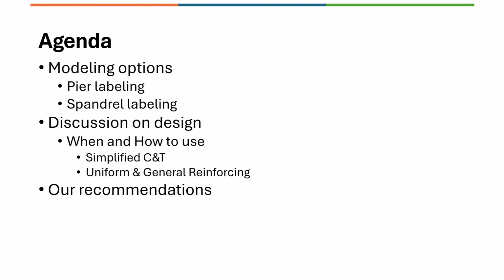Here in this session, we will be discussing the methods available within the shear wall design module in detail. Okay. So I will start with the modeling options, and then the discussions will enter the design, like when and how to use the simplified C and T or uniform or general reinforcing. And along with that, we also give our recommendations.